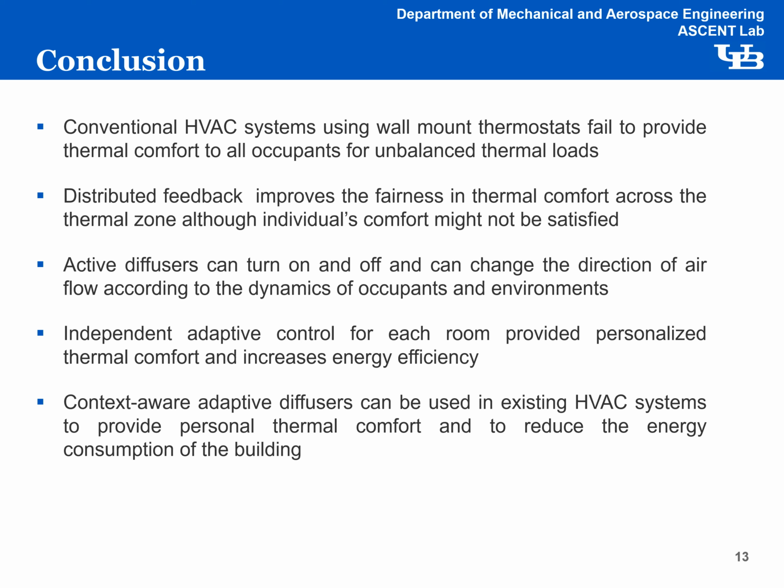In conclusion, the simulations showed that rooms require different conditioning time depending on their thermal load. Therefore, a conventional HVAC system fails to provide thermal comfort when the thermostat in one subspace controls the HVAC operation of the entire space. Distributed sensors provide additional feedback to control the HVAC operation and can improve the fairness of thermal comfort where thermal load is imbalanced.